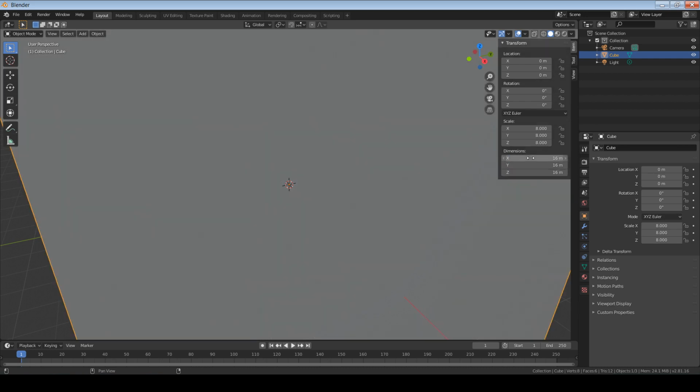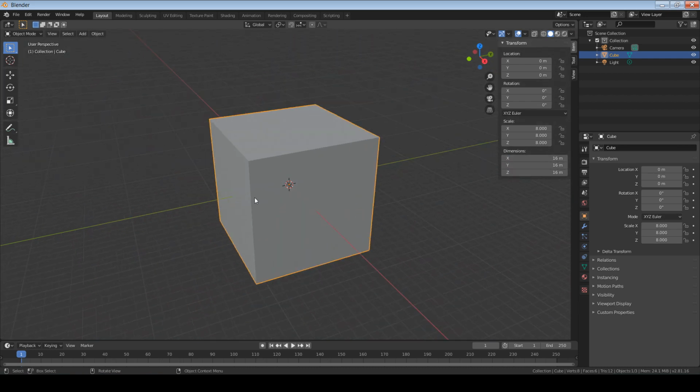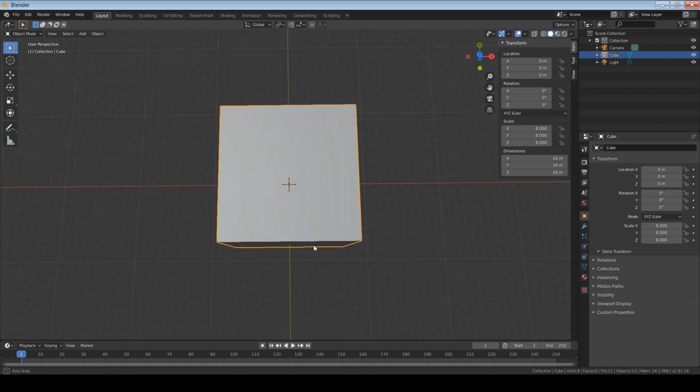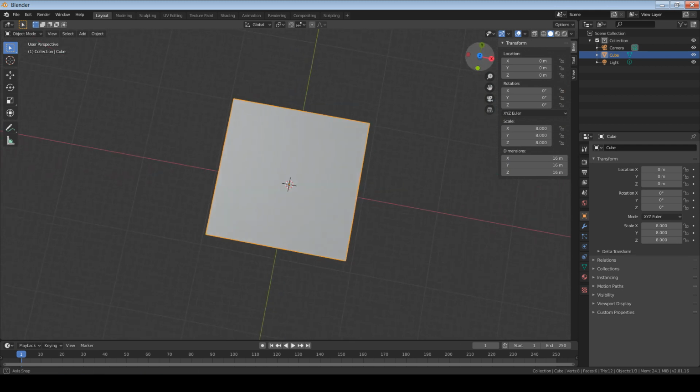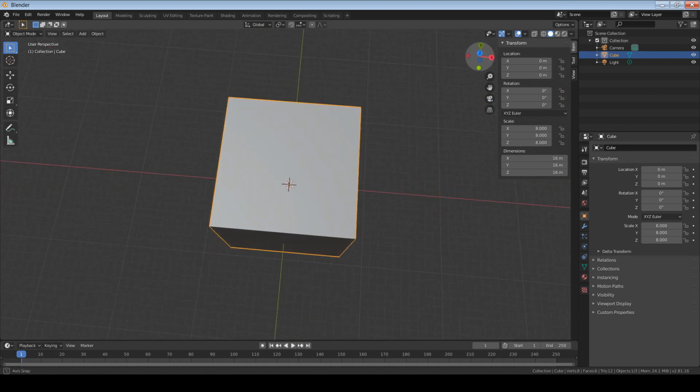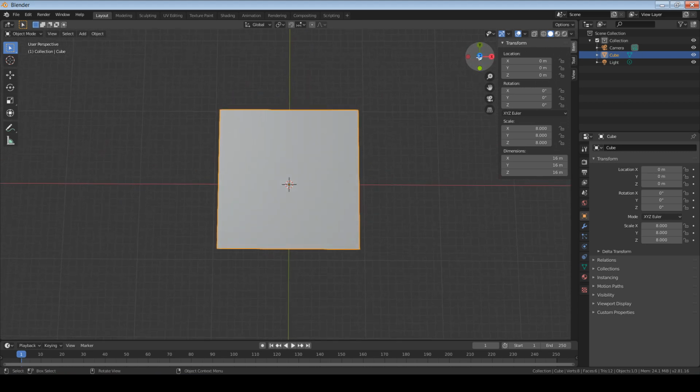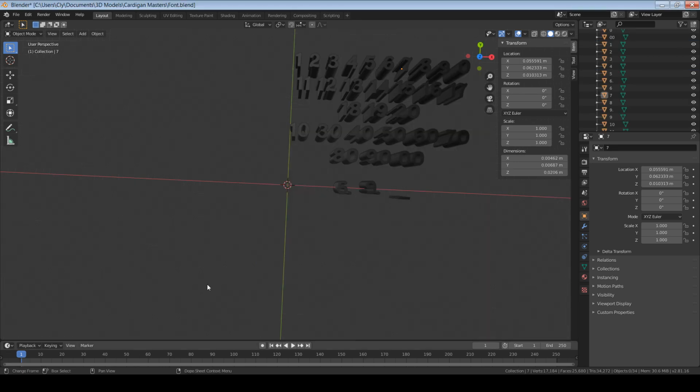That's right, I said meters, because for some reason, whenever I export a model from Blender and then import it into my 3D printer's slicing software, it's 1,000 times smaller than it's supposed to be. And that's actually pretty common. However, if you don't encounter this with your 3D printer's slicing software, feel free to convert all of these measurements from meters back to millimeters.